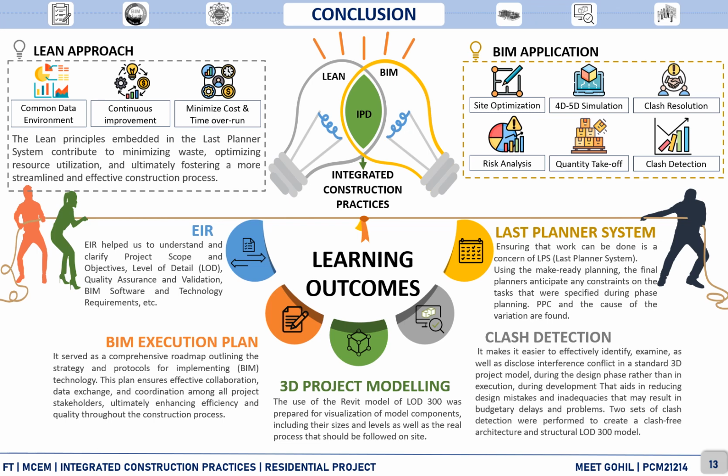Implementation of lean, as in the last planner system, on the project ensures that work can be done using make ready planning. The last planners anticipate any constraints on the tasks that were specified during the phase planning. The planned percentage completion and the causes of the variation were found and nullified. Thank you.